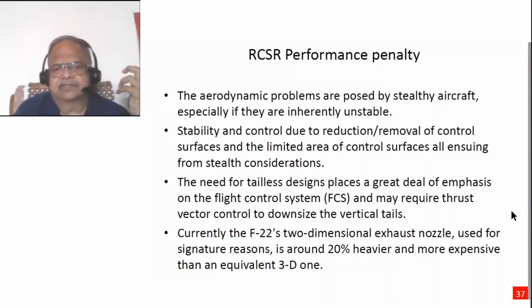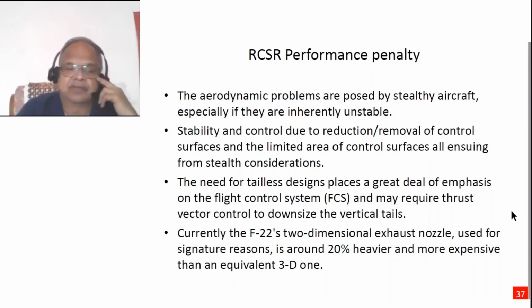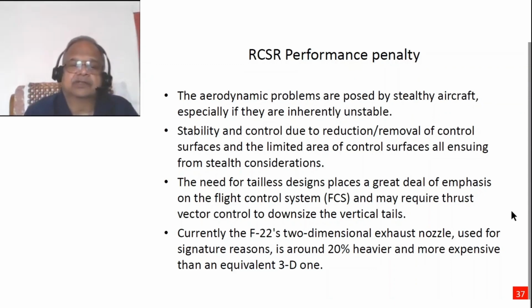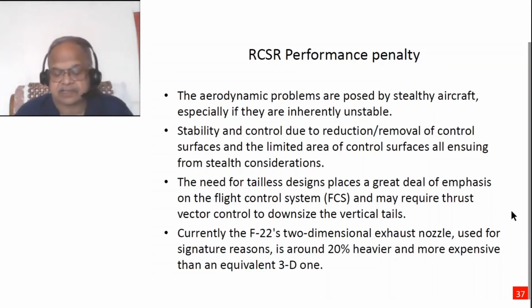The need for tailless designs places a great deal of emphasis on flight control systems. Flight control systems are nothing but a system containing computers, actuators, programs, and a huge aero database based on which the decisions are taken, all on board. Because of the lack of some other control surfaces, one way which has been addressed is thrust vector controlling, and that is basically deflecting the nozzles to be able to achieve better controllability.